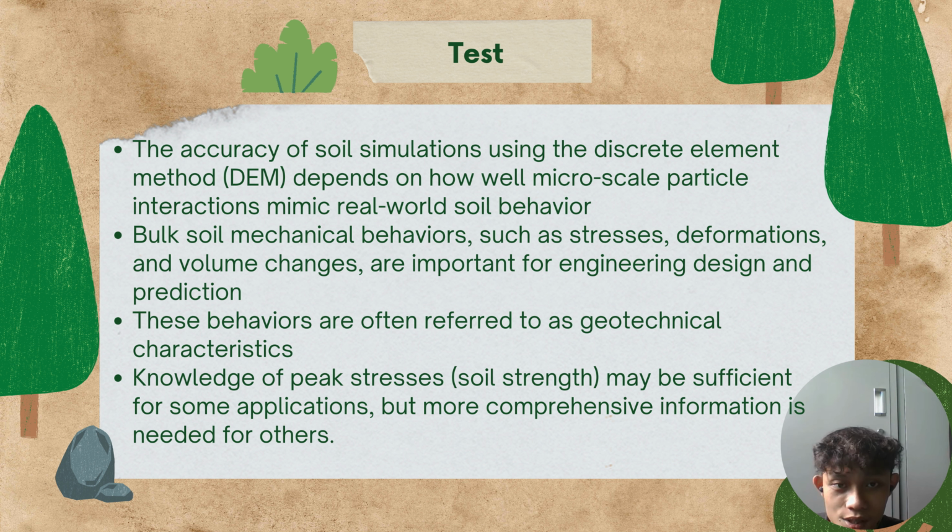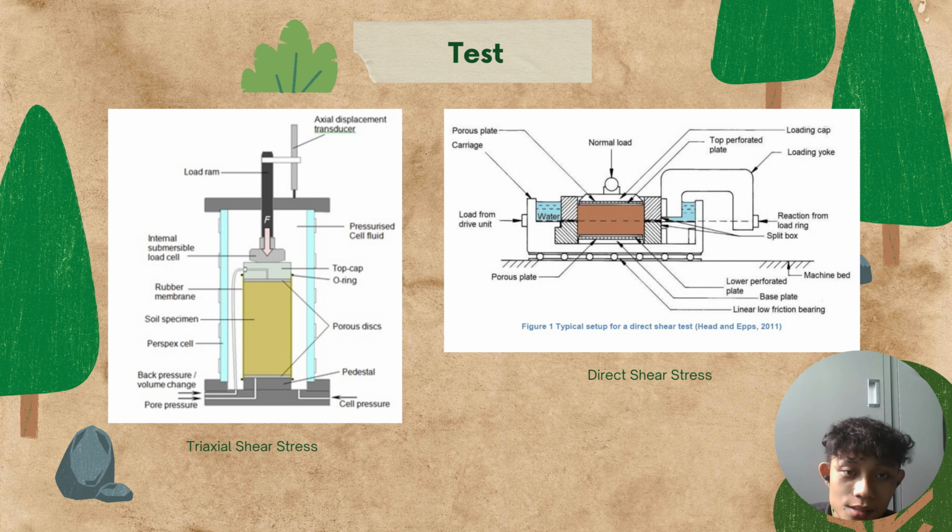Triaxial shear, direct shear, and tensile strength laboratory tests are frequently used to determine soil geotechnical parameters. Penetrometer force is frequently used to evaluate in situ soil mechanical characteristics as a result of penetration depth measurements or other in situ tests. The microscale DEM parameters that generate the best fit between physical soil bulk mechanical behavior and DEM are identified using DEM simulations of physical geotechnical testing.